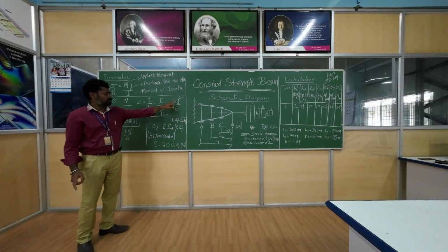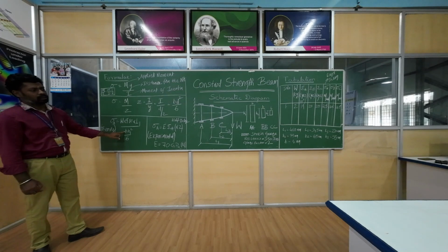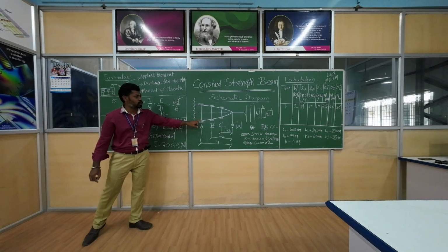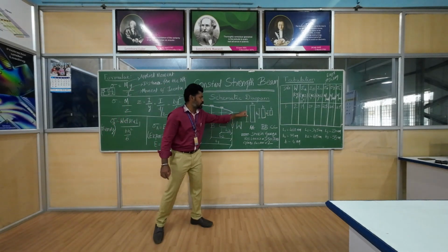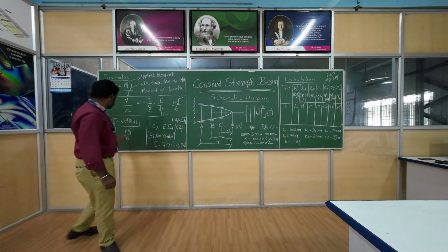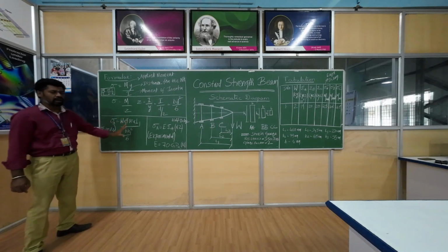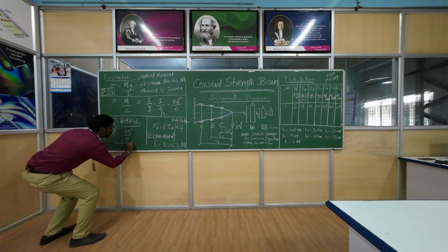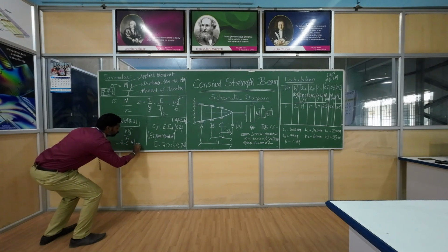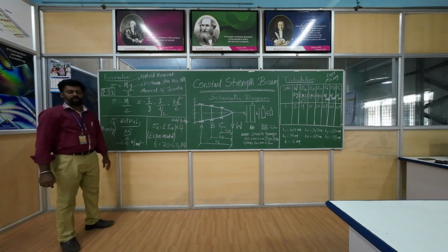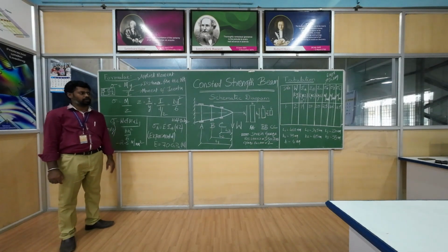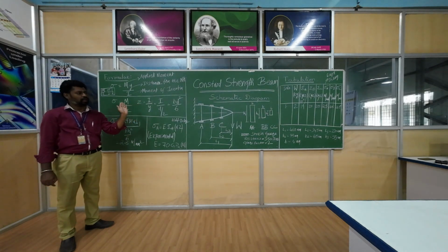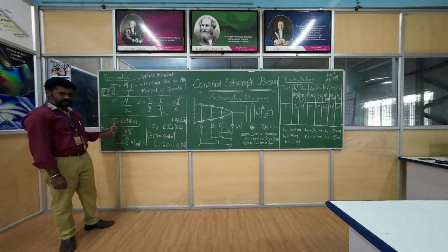So here I have given the formula. B is the width of the beam, and at section A we have a depth of h1. You can see here, apply the h1 value, which is 75 mm, squared, divided by 6. If you plug in all the data, you get the stress to be around 2.6 Newton per millimeter square. This way, we can prove that the stress in the beam is constant at all the sections along the length of the beam. We have done it for A.